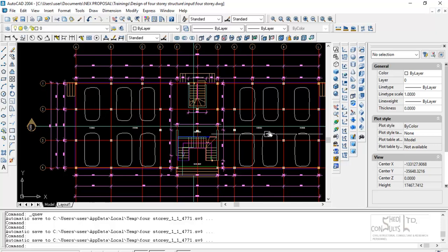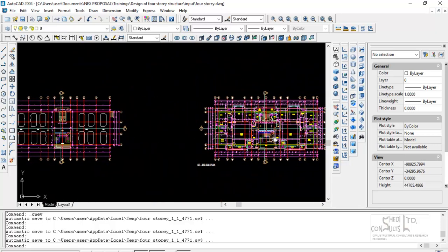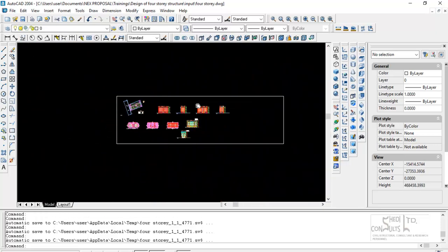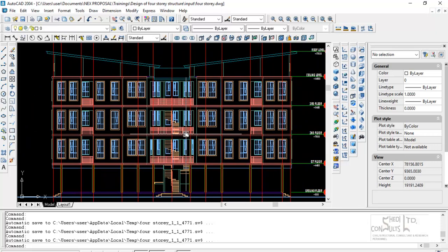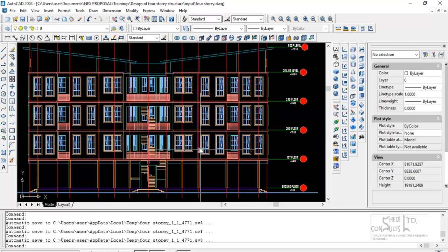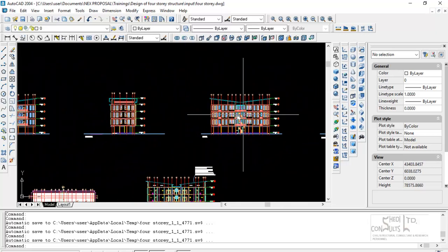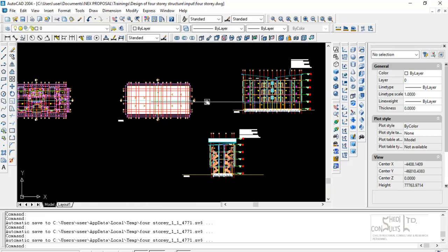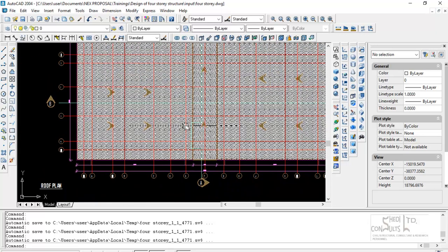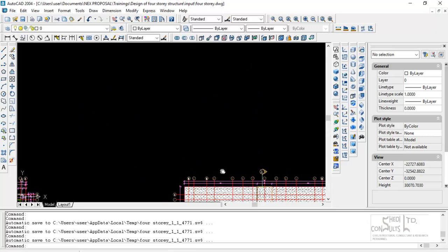Another form of in situ testing done on site is what we refer to as the standard penetration test. Standard penetration tests are usually carried out on granular soil materials. You don't carry out standard penetration tests on cohesive soils, because these are plastic soils with most likely collapsible properties. So standard penetration tests are carried out on cohesionless, granular soils such as sand, medium dense sands. You drive a standard